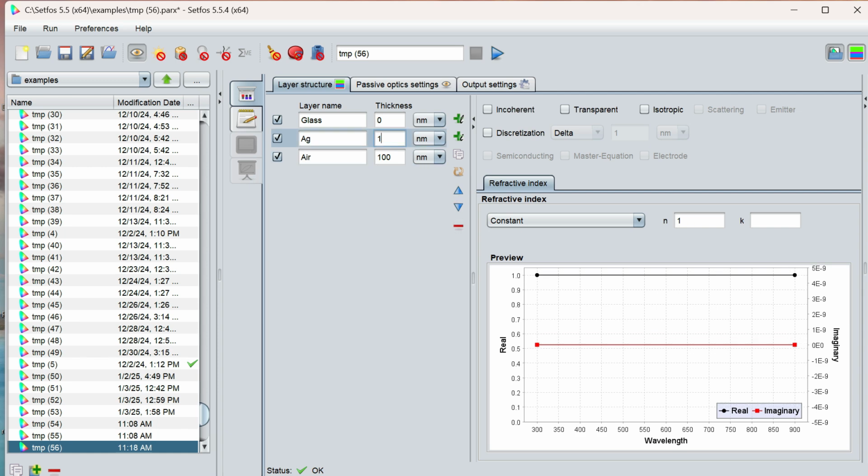You can provide the thickness value here for the glass. Here you can give the new value for the refractive index of the materials. Top and bottom layers are semi-infinite media, so thicknesses are irrelevant here. So we are considering 0, 0.